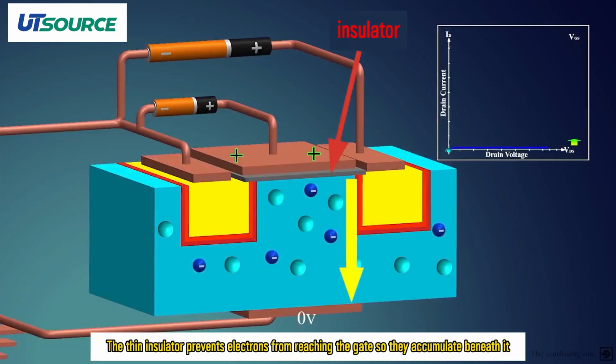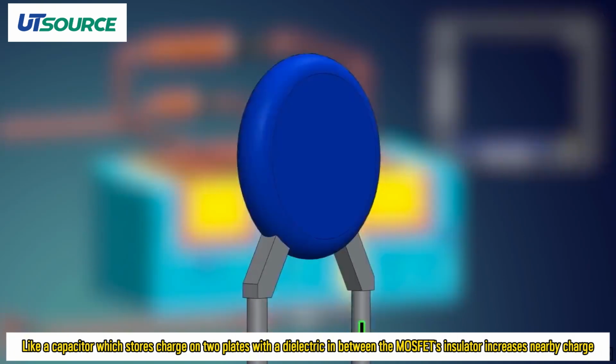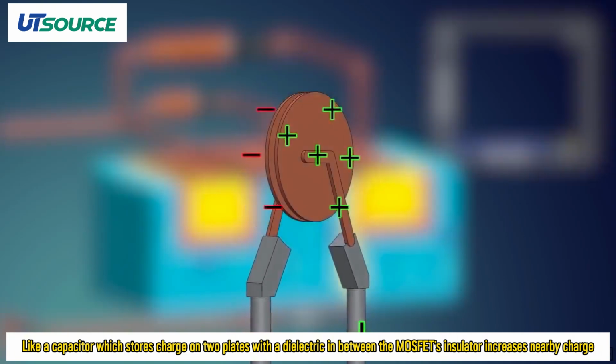The thin insulator prevents electrons from reaching the gate, so they accumulate beneath it. Like a capacitor which stores charge on two plates with a dielectric in between, the MOSFET's insulator increases nearby charge.